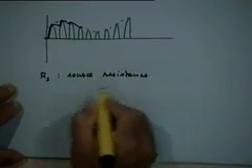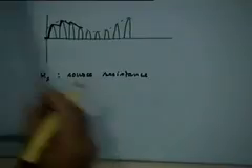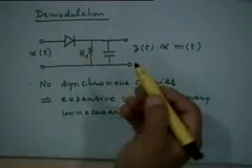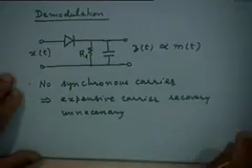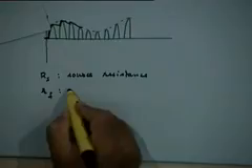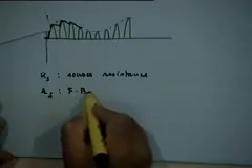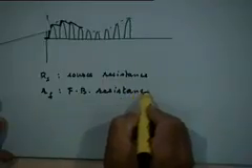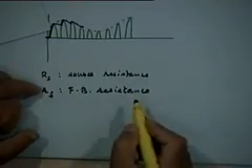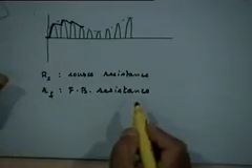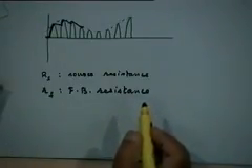And let us say the forward bias. During the forward bias the diode behaves like a simple resistor with a small resistance equal to R sub f. So we can call it the forward bias resistance of the diode, right? Typically both the source resistance, the source impedance, and the forward bias resistance are small values.